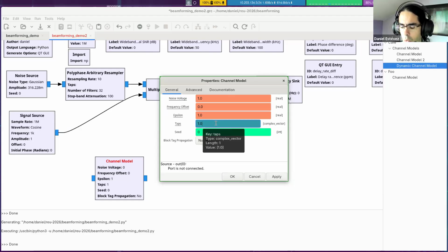So the thing is that when you have something which is called multipath, which means that the radio frequency signal arrives to the receiver through multiple paths, because again, coming back to the example of radio frequency propagation in a city, there can be a direct line of sight path, which is the straight line between the transmitter and receiver, but then maybe the signal reflects off a building, and so there is another path which has one reflection, and there can be many other more complex paths involving multiple reflections. So all of these paths will contribute to what the receiver sees.